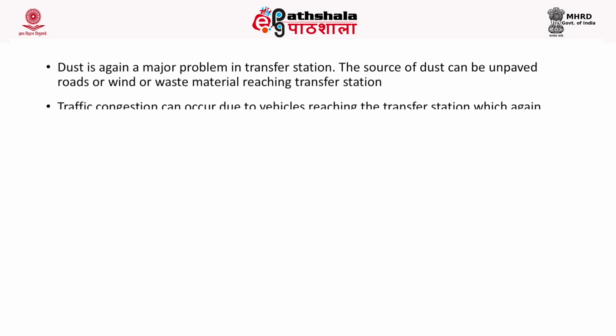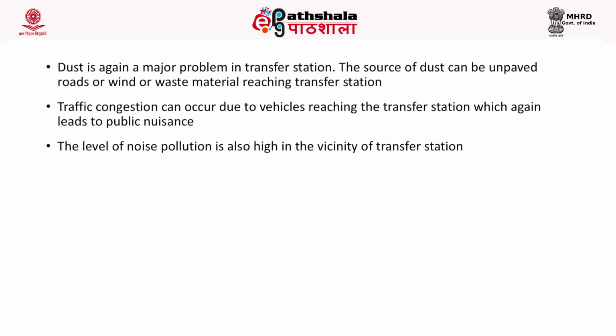Again, dust is another major problem in transfer station. The source of dust can be unpaved roads or wind or waste material being carried off from the transfer station. Traffic congestion can also occur when vehicles reach the transfer station at same point of time. This can also lead to public nuisance. The level of noise pollution is also high in the vicinity of transfer station. Now, these are the problems which generally limit the application of transfer station in a waste management plan.